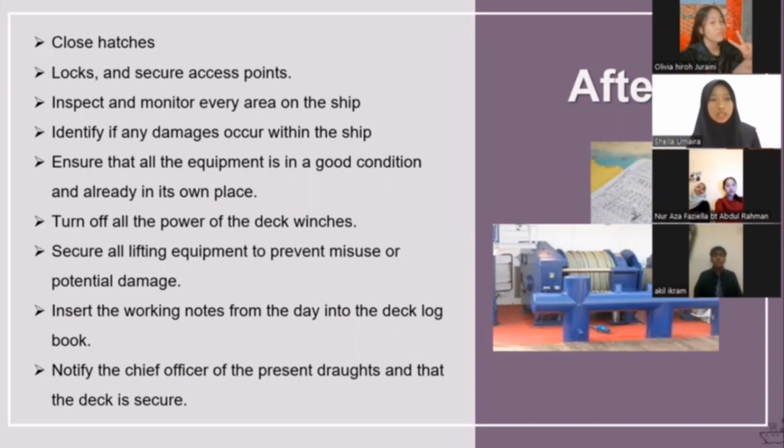After that, ensure that all the equipment is in good condition and already in its own place. After that, turn off all the power of the deck winches. The deck winch is this blue thing in this picture, because before we do the cargo operations, we turn on that thing, but after, we need to turn it off again. Then we need to secure all lifting equipment to prevent misuse or potential damage.